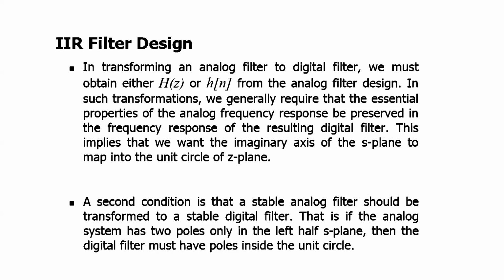I'm giving an example. But if you use an IIR design strategy to design a filter with the same set of specifications, the IIR filter may require an order of, let us say, 10. So that is the difference between implementing filters through the FIR strategy or the IIR strategy.